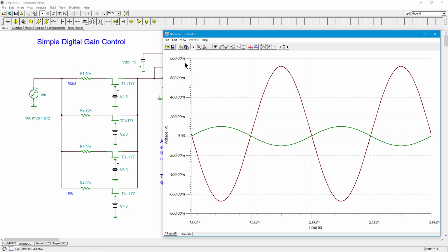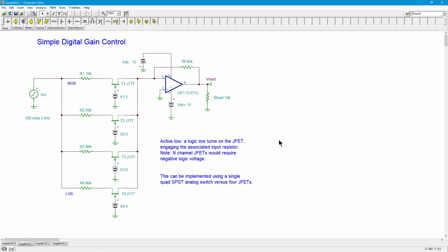And voila. Okay, so I can see there's 700 right there. I think it's pretty much the same kind of offset issue we had last time. Yeah, so we're a little over 700 millivolts, and we're a little bit negative of 700, so yeah, that works great, okay? If DC offset is a problem, you could just put a coupling cap out here, right? All right, so